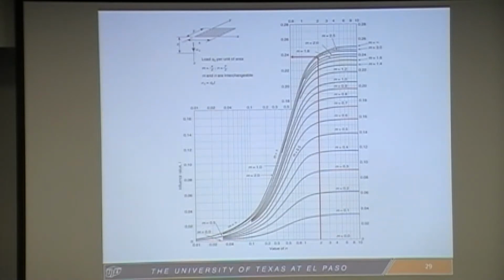And remember that these are reduction factors, meaning that you multiply that by the stress on the surface, and it's going to be smaller than that. In this case, that number is going to be roughly 1/4 of the contact pressure, 0.124, 0.125 here. That's the implication of that.